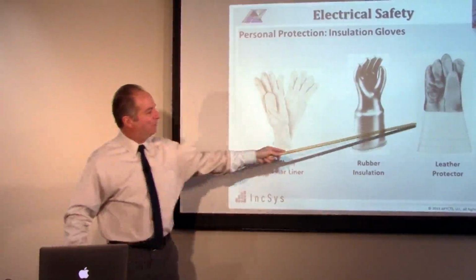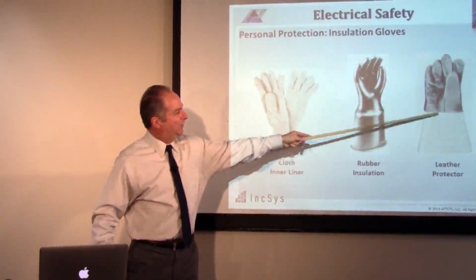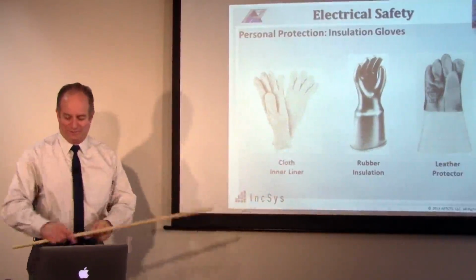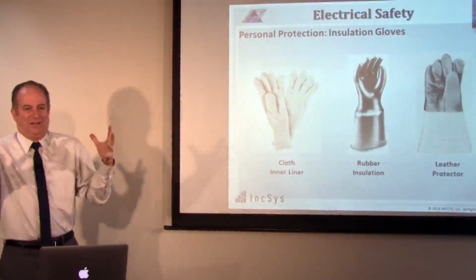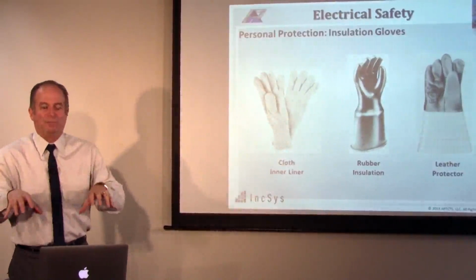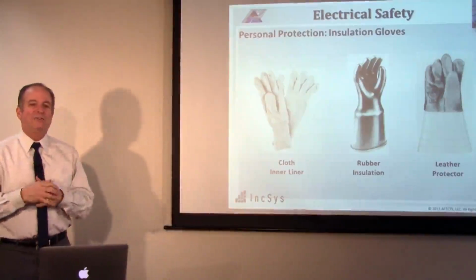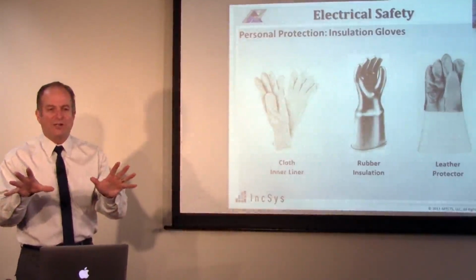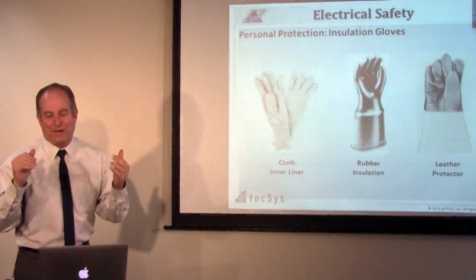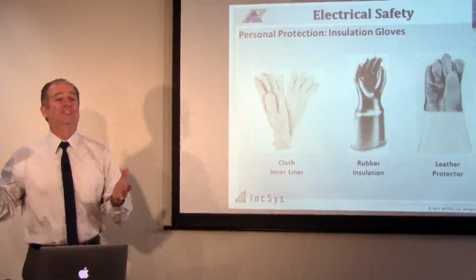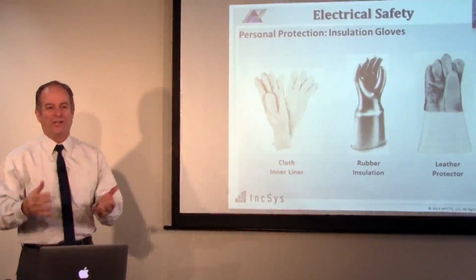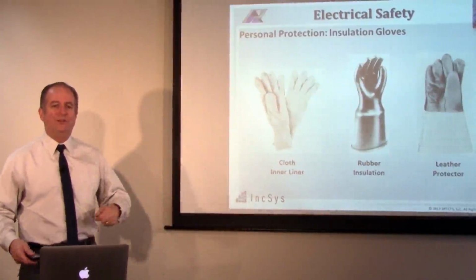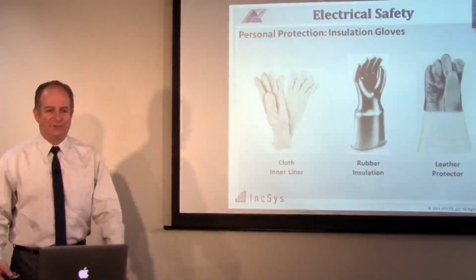And then you have a protective leather glove that slips over the insulating glove, and you work with these big gloves and you're trying to do work with them, but you're protected with 20,000 volt type isolation. Then you can actually touch energized lines, or if a line might be de-energized but accidentally became energized, you're already protected. So this is a form of personal protective equipment, rubber gloves.